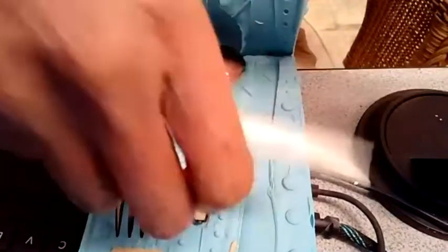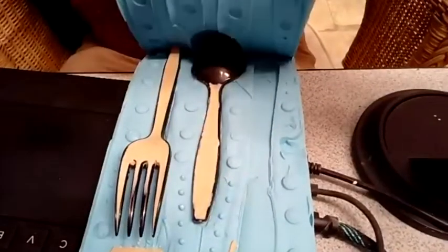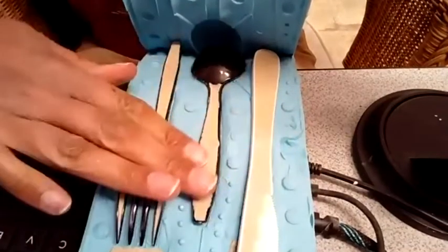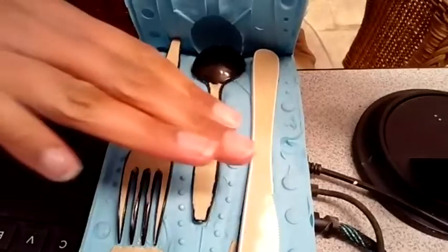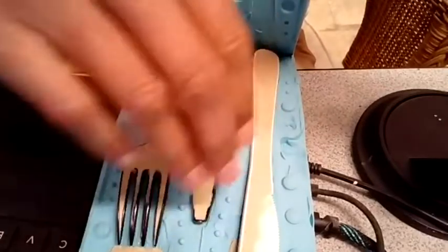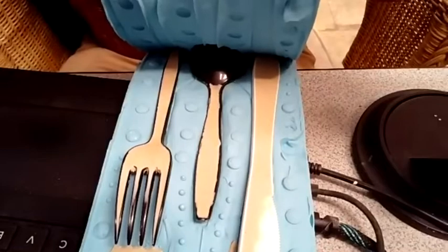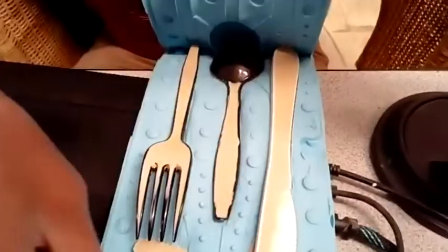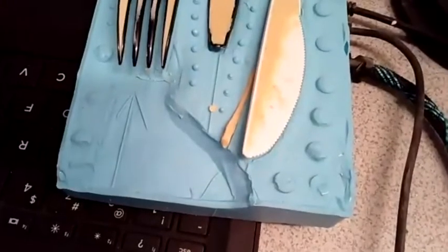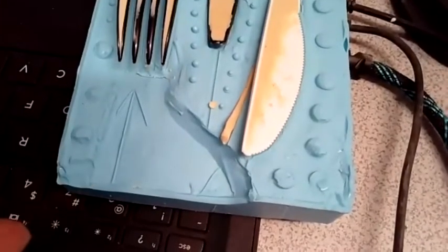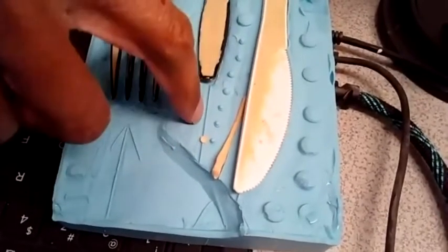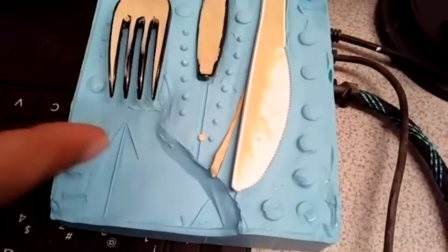The bottom mold took about a day to dry. And then I did the same. I flipped it upside down. These three utensils were sitting in clay. So I turned it upside down, peeled the clay off, and then poured this shape on top of the top portion. So this is still a little sticky. This area is where the resin will flow inside here. And all these little gaps are what allows the air bubbles to escape as the resin is pouring inside here.